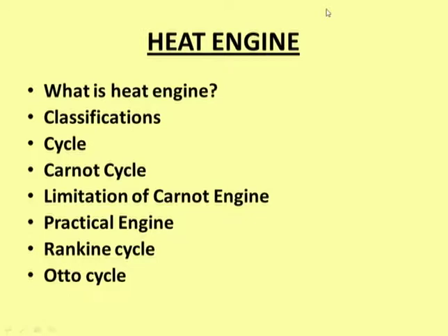In this context, we have seen the Rankine cycle, where the vapor of H2O is used. The main components of the Rankine cycle are boiler, turbine, condenser and pump. We have derived the efficiency of the Rankine cycle and solved a small exercise based on it.